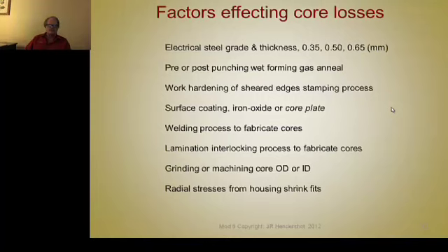But if you use stamped laminations and you stack them up and you weld them by heating the material in a fine bead or a fine line using a laser welder or a TIG welder, a tungsten tip with inert gas environment, and you don't add any filler metal, there's no way you could build up and have the OD be larger than the lamination from that weld, because the stamped edges have a breakaway side.